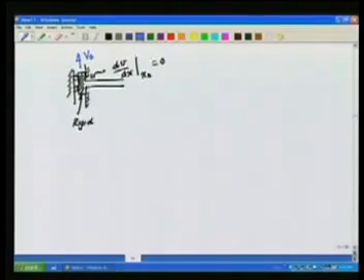Okay, and accordingly, because dV/dx, for example, here is fixed, so I have to go and constrain the dV/dx to be equal to 0 in my final system. So once I have obtained the element calculations, done the assembly, then I appropriately apply the boundary conditions, that is, add either the boundary forces and moments or constrain the boundary displacements or the slopes to be the given values. Okay. Again, the same procedure that we had followed.